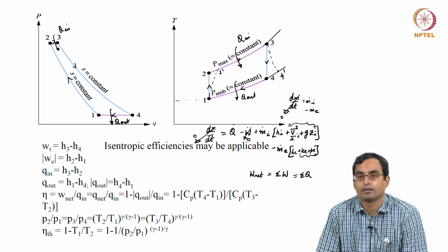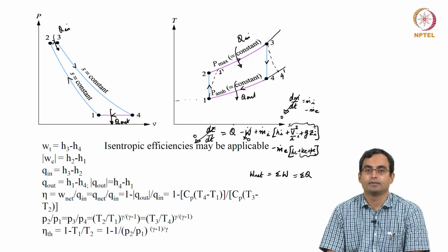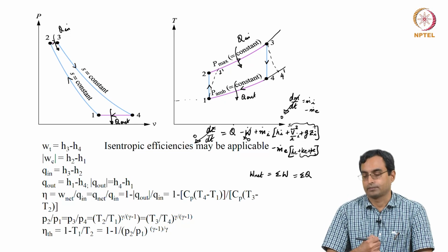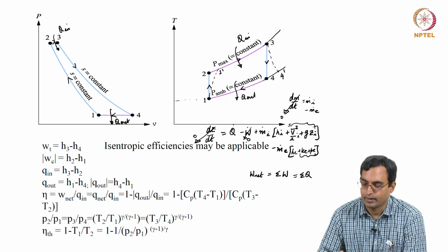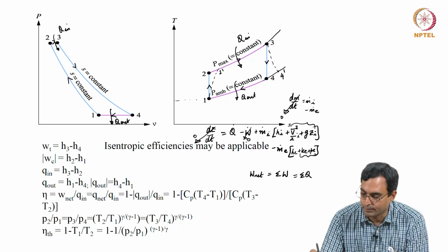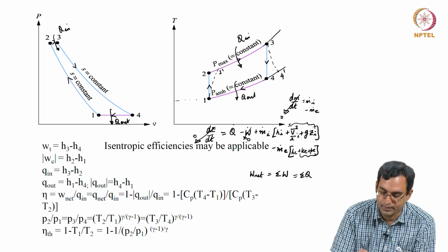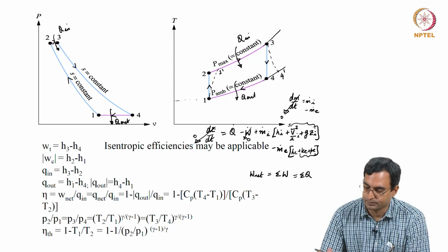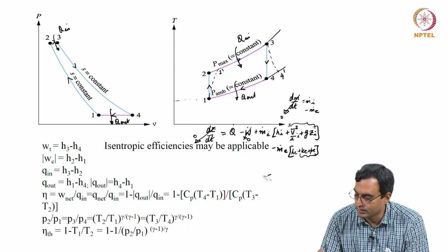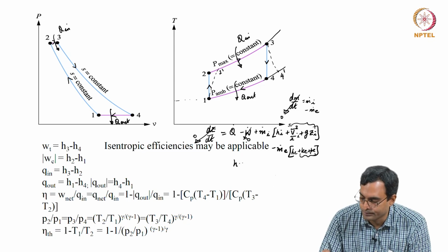This is the standard Brayton cycle or the standard Joule cycle, the working substance is essentially air. We can assume air to be an ideal gas. So, if we assume air to be an ideal gas, we can write these enthalpies, whatever we have here, in terms of Cp and temperatures. If we assume also that Cp is constant, then we have H is some Cp into T.